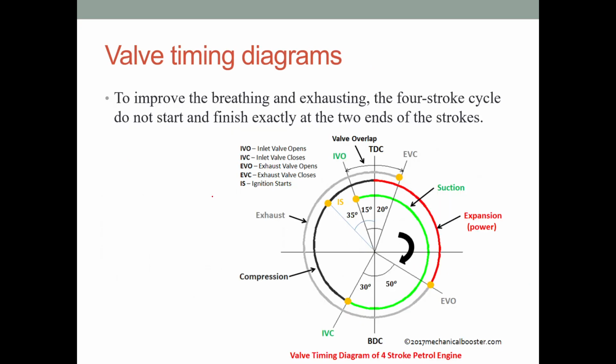So the valve timing is also important, but again, it's not the main focus of this class, but I'll discuss it quickly. So at the beginning, the inlet valve is opened. So we are at this point, and then the suction is going to happen all the way here. And then at this point, the inlet valve is going to be closed. Then we are going to have compression, all this black line, and then it gets to TDC, and ignition is going to happen, and then we have power, which is this red line, up to here.